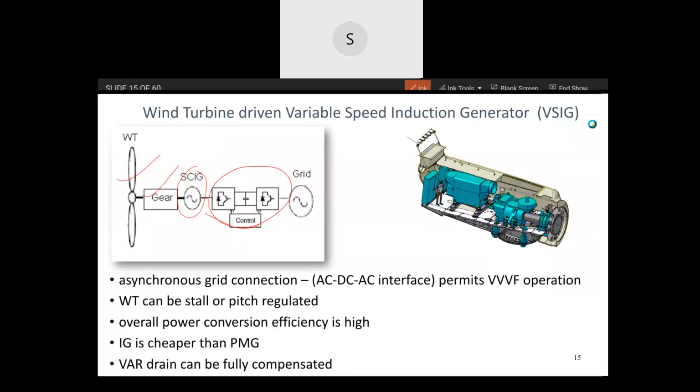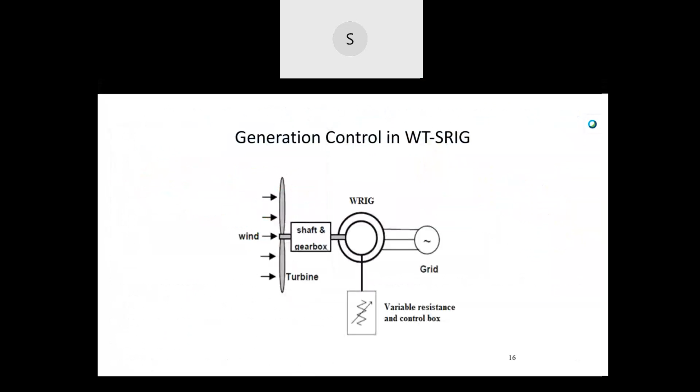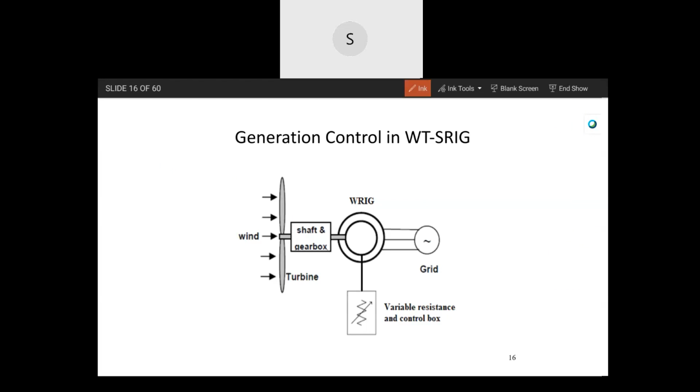This is the story with the large wind turbine generators, grid connected. I said in the beginning, it cannot be considered for microgrids. But otherwise, this is the existing technology. Now, even the slip ring induction machine doesn't need to be used as a DFIG. It was tried and developed by Suzlon in one of their models. On the rotor, you can have an external resistor and use it to vary the slip. Sometimes when sudden power surges occur, this is helpful for control.